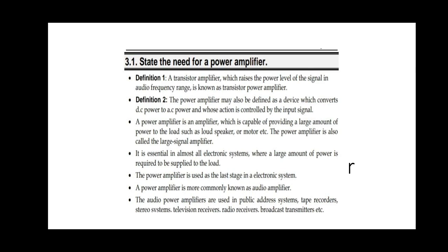Similarly, for input impedance, voltage series input impedance increases, current series input impedance increases, voltage shunt and current shunt input impedance decreases.